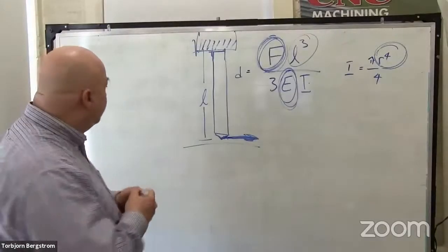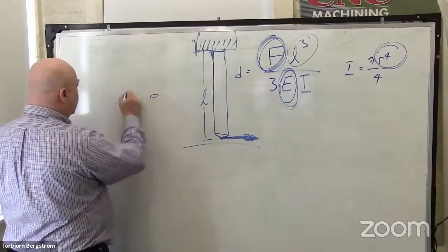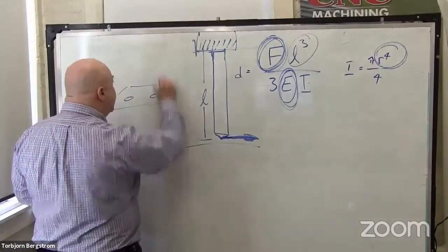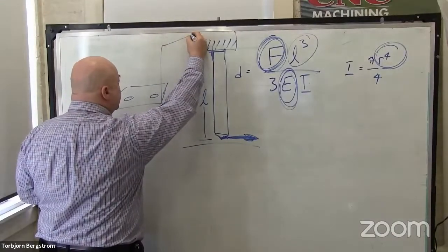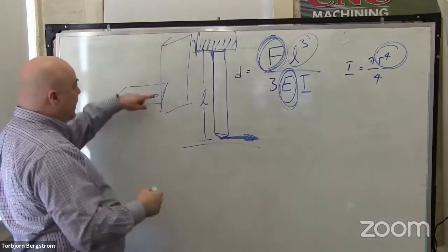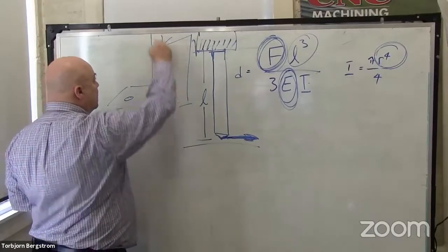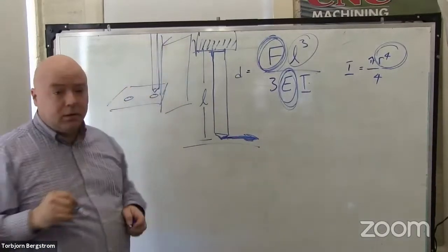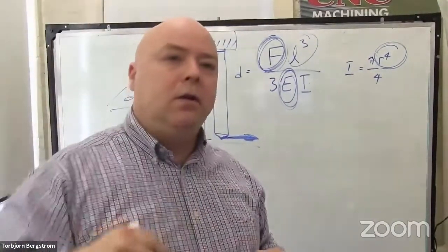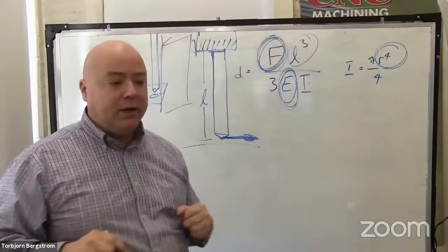Okay, so if we needed to put holes here in our piece, and we had a big feature that was tall next to it, not really good at drawing in 3 dimensions, but you get the idea, right? You might then have to have a really long drill in order to make this hole. I might not be able to use a short stubby drill because I may not be able to get the spindle close to this without crashing into the big tall thing next to it.